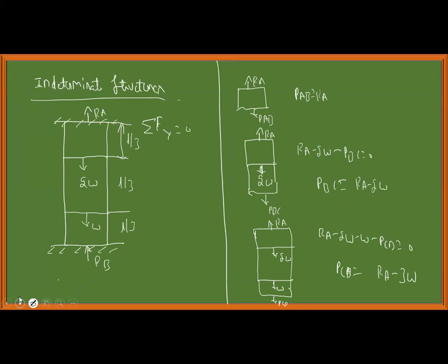The total deformation is equal to 0. The bar cannot extend overall. If this section extends by 2 mm, this one contracts by 1 mm and this also contracts by 1 mm, so the total deformation of this bar is 0. Since it is constrained at both ends, even though deformation happens at each section, the entire structure has 0 deformation. Okay, now we'll go ahead.